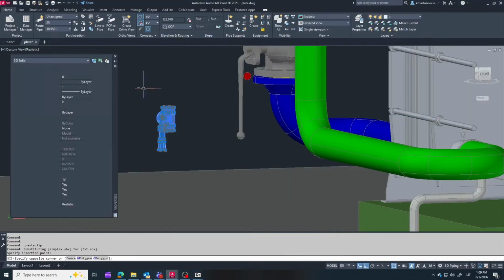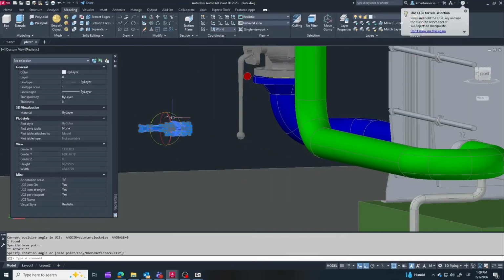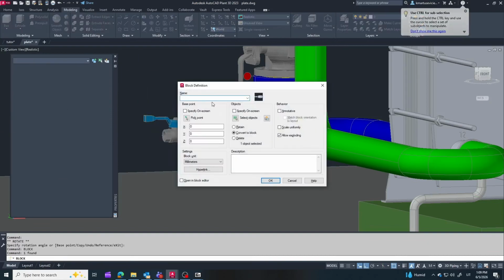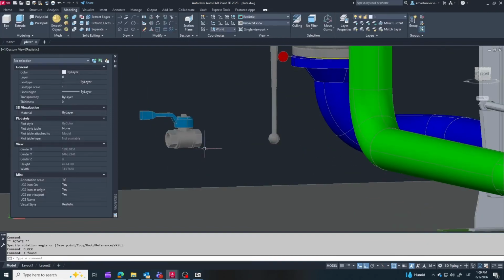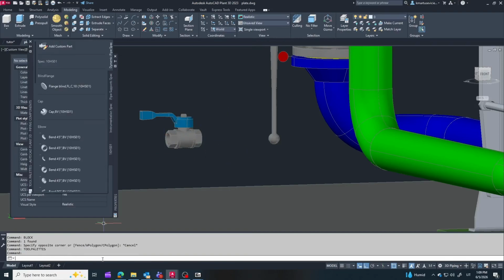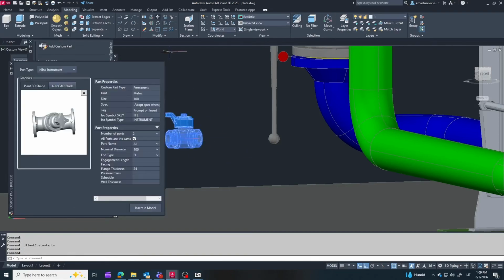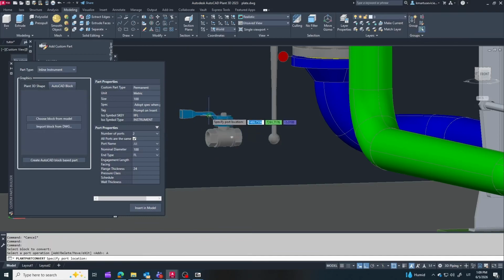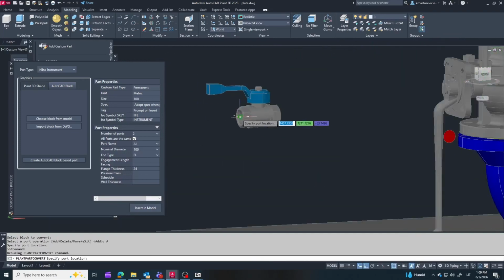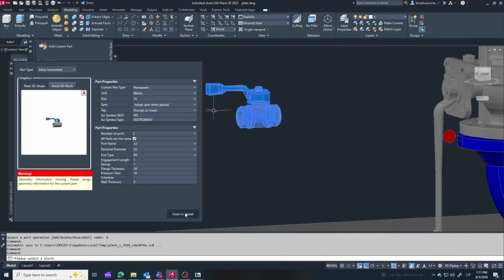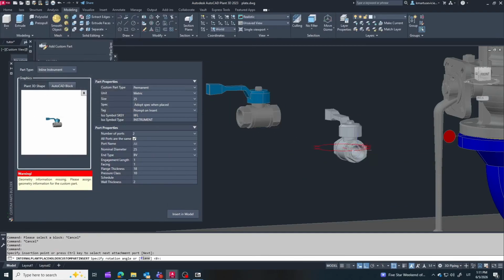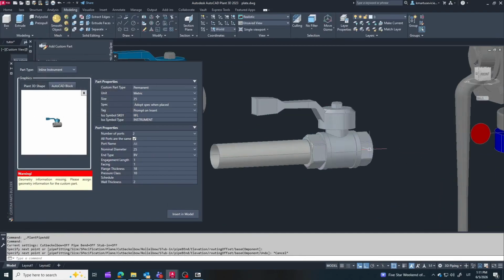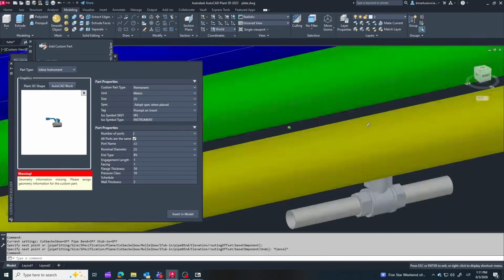When converting this valve into a live component, I'm actually going to select plain ends instead of threaded ends. Here's a quick Plant 3D tip. If you choose threaded ends in the software, AutoCAD often forces bulky box-type couplings onto the joints, which unnecessarily clutters the 3D space. By using plain ends, we keep the model clean and lightweight. Then, we simply specify in the valve's datasheet and catalog properties that this is a threaded component. It's a much smarter way to manage your project data without messing up your visuals. And there we go. Here is the final, realistic look of our threaded valve in place.